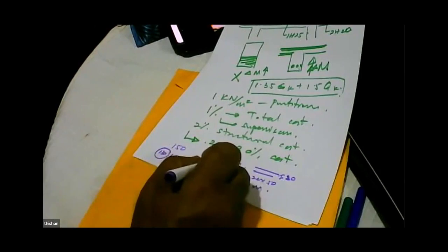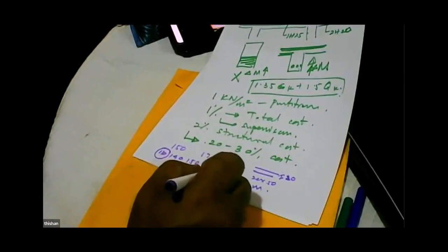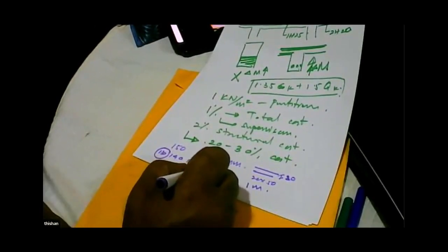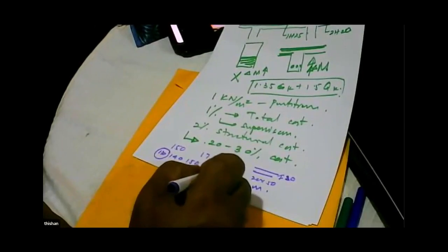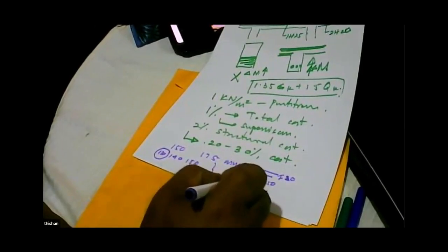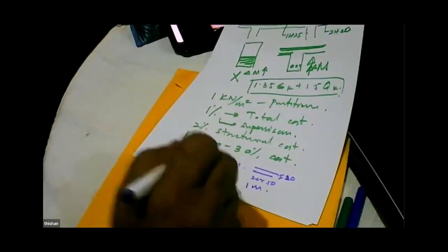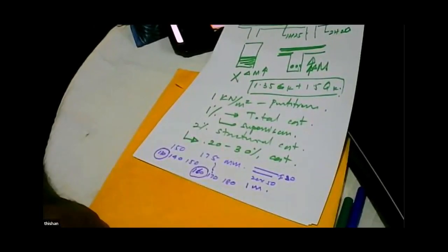Right? So if you need 175, as you look at it, you try 150, 160, 170, and 180. Most likely it will be 160 that you can manage. Or sometimes you find 170. Sometimes, because of deflection criteria and so on, 170 actually gives a more economical design, because it needs less steel, though it needs a little bit of concrete extra. The concrete is a very cheap material. If you save a lot of steel, it is going to be cheap.